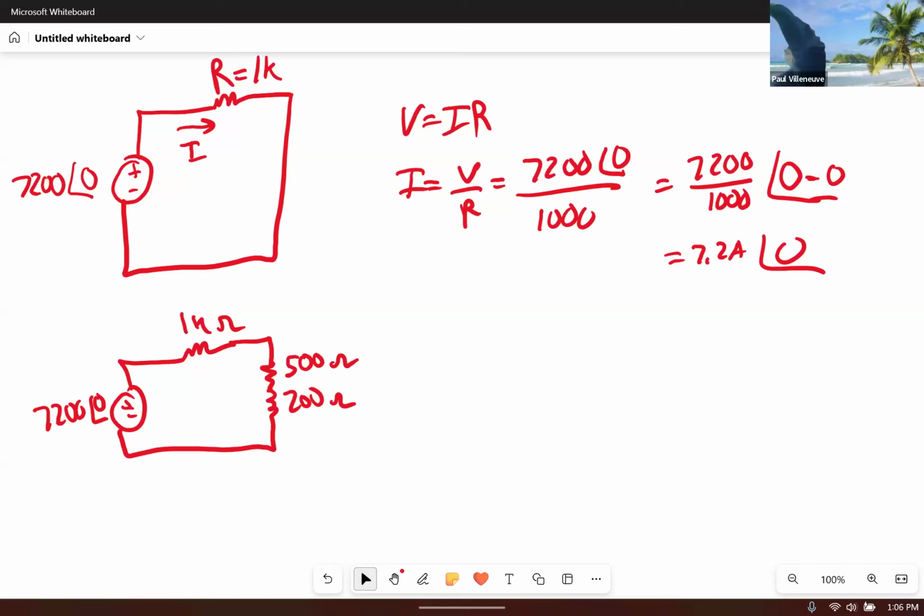The current went from, let's say, 5 amps to 0 amps instantaneously. What is L di/dt equal to when you go from 5 to 0 instantly? What's the derivative, the change in Y over the change in X? It could be positive or negative, it doesn't matter, but it's going to generate an absurdly high voltage, isn't it?